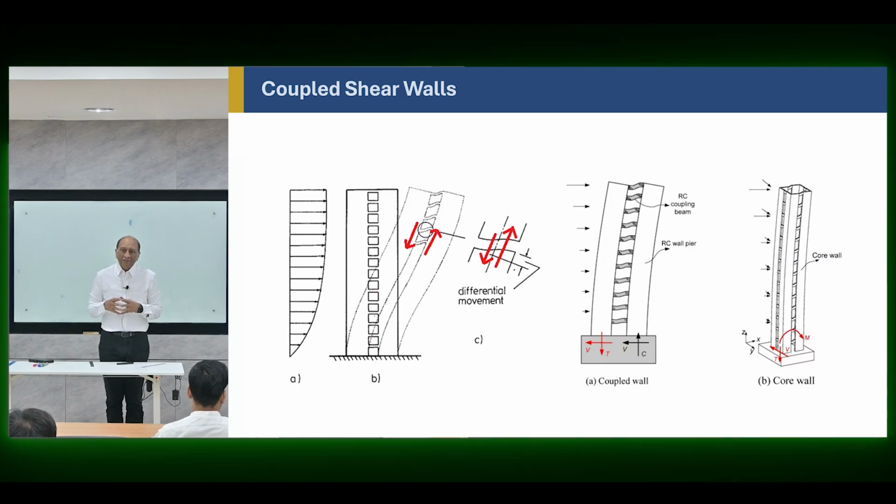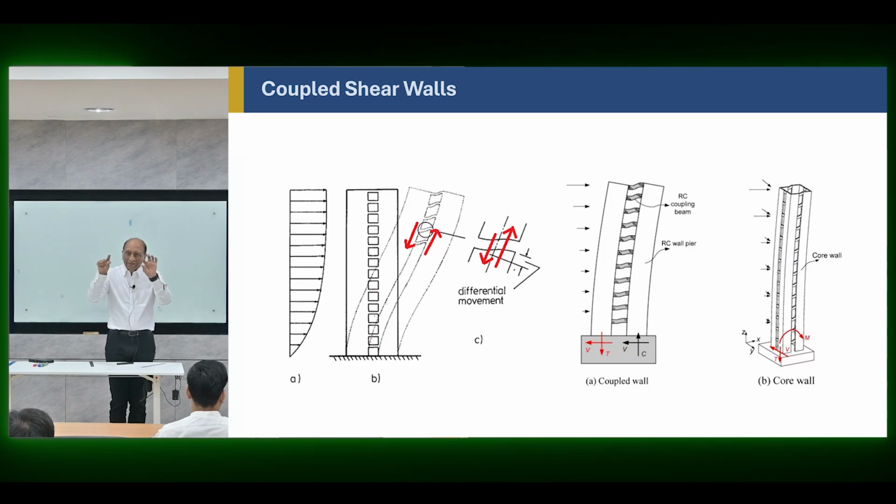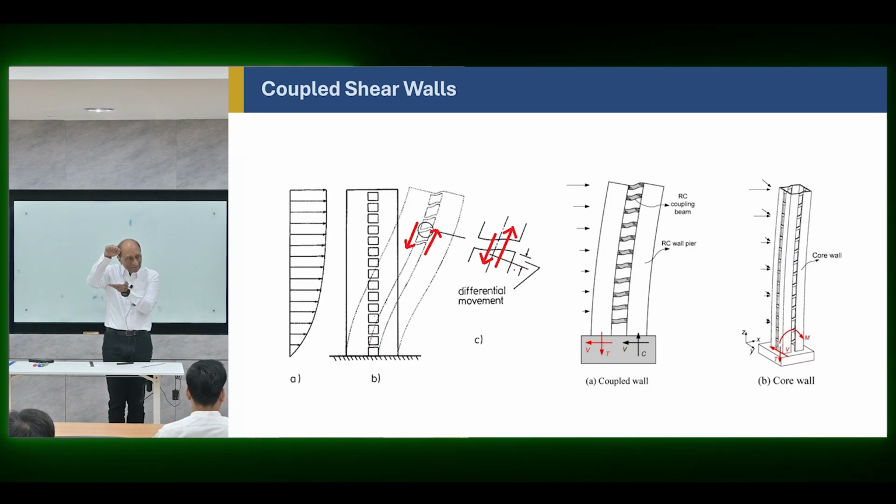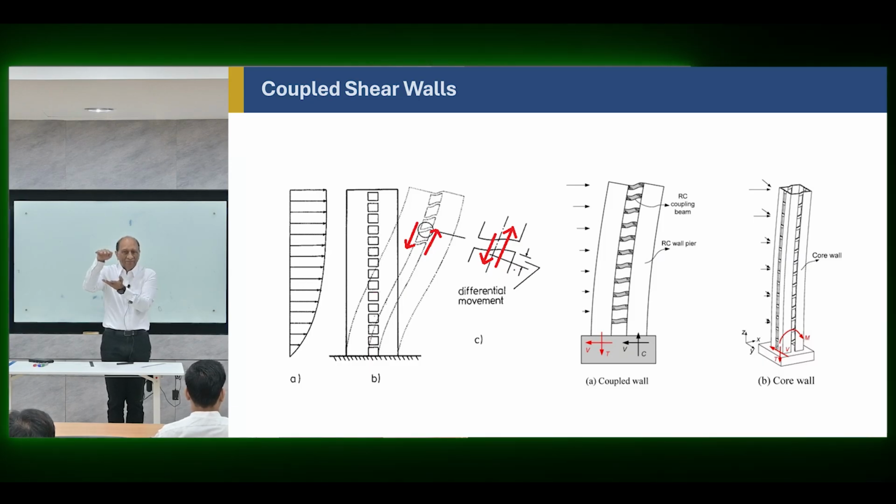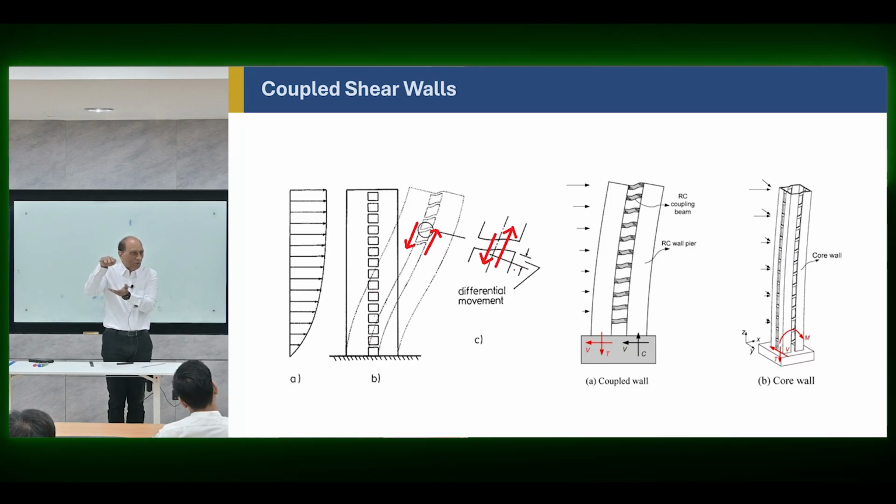And the problem is that their bending moment, when you connect them together, depends on their size. So if you make them deep, because of the short length, they will attract a lot of shear and a lot of bending moment. And if the capacity is not enough, then you try to increase them. When you increase them, they attract more force.